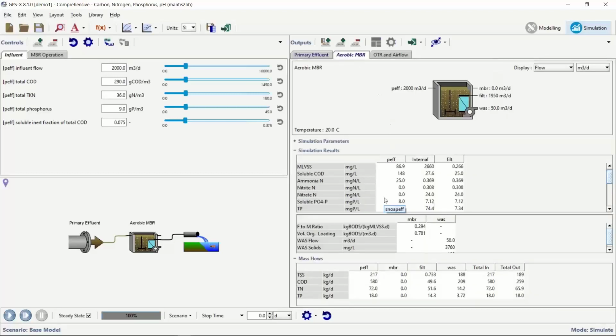One thing to note is if I go back to this panel and slide down a bit, our DO is actually 3.5. That's a little higher than you might expect because we've got this excess aeration for the cleaning. This is interesting and complex behavior for the DO controller.